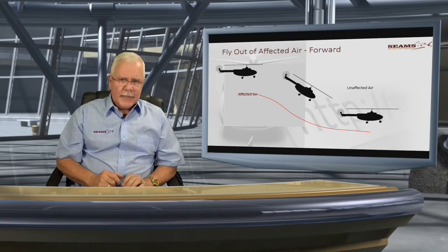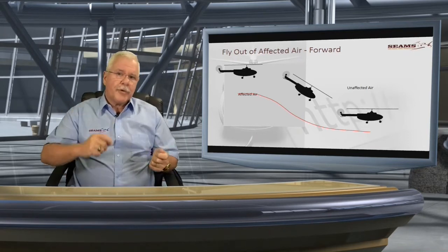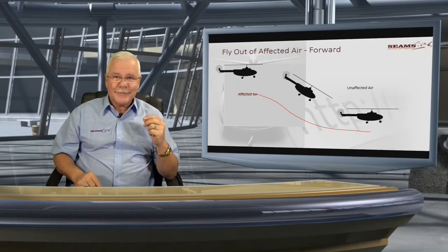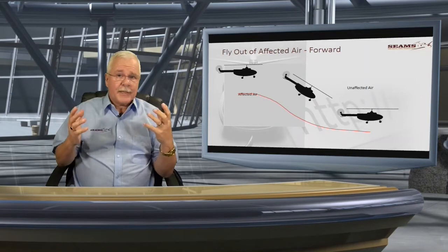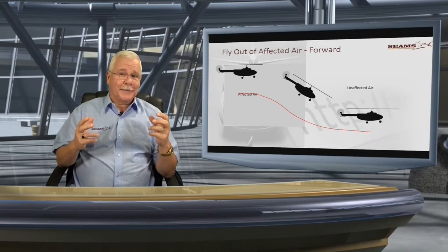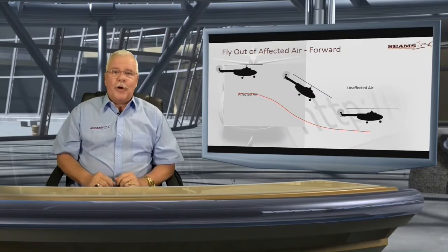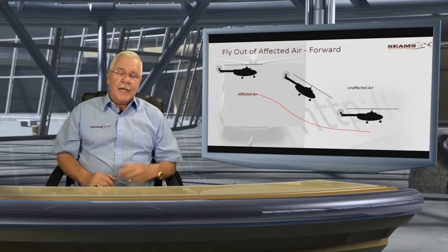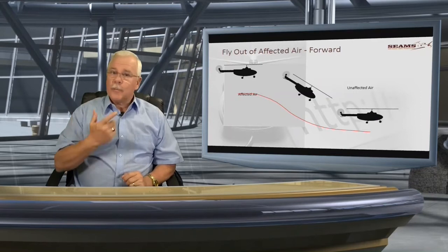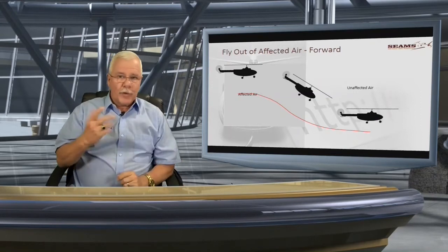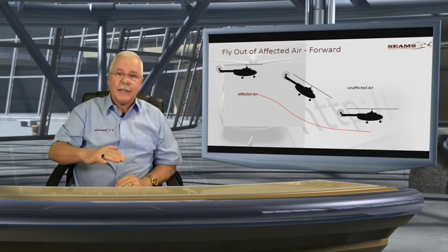Yeah, but Charlie, it doesn't make sense because the rotor RPM drooped because I had too much collective. No, it wasn't because you had too much collective, you had too little power. But then it's hand in hand. Doesn't really matter, does it? The main rotor RPM has now drooped. You haven't got main rotor RPM to sustain your flight. And as you pull power, the main rotor RPM will just get less and less and less. Therefore, you want to go down. Your problem is now you've got no speed, you dump and you descend faster.